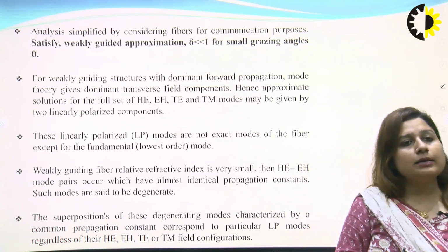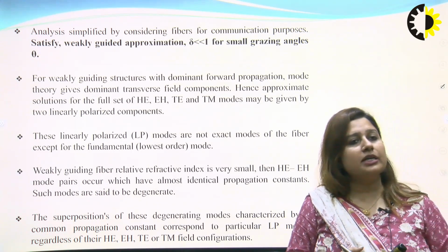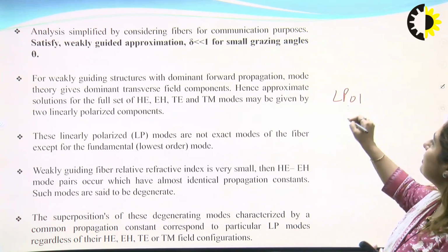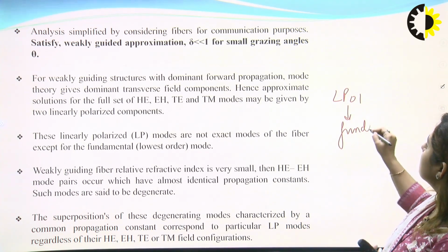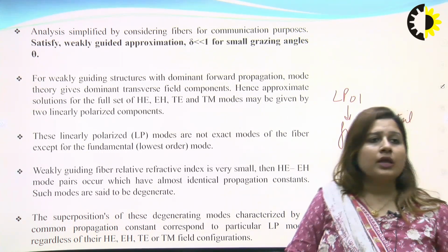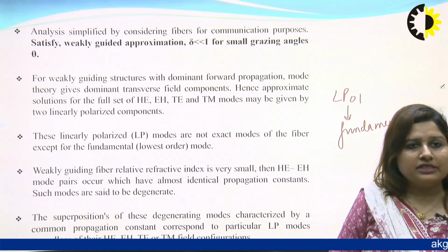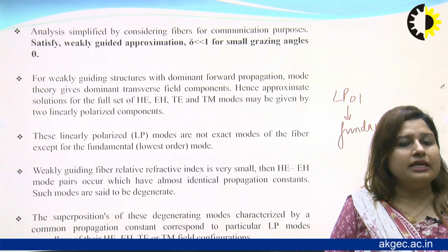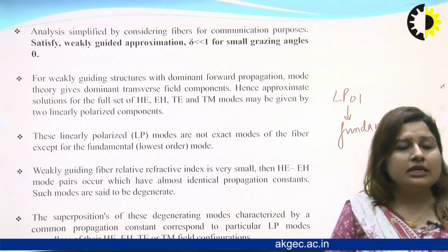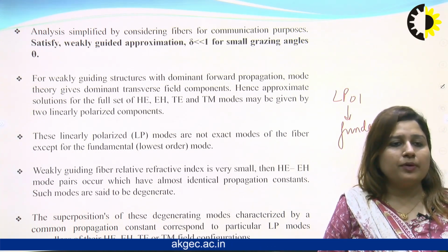These linearly polarized modes are not exact modes of the fiber, except for the fundamental lowest order mode, which is called LP01. In a weakly guiding fiber the relative refractive index difference is very small, so HE and EH mode pairs occur which have almost identical propagation constants. Such modes are called degenerate modes, having the same propagation constant.